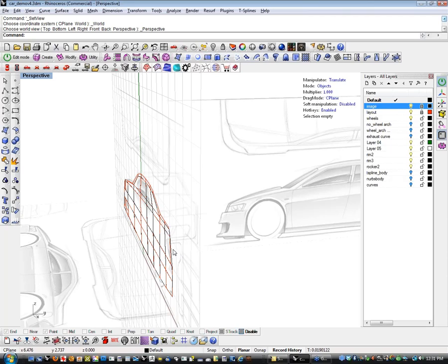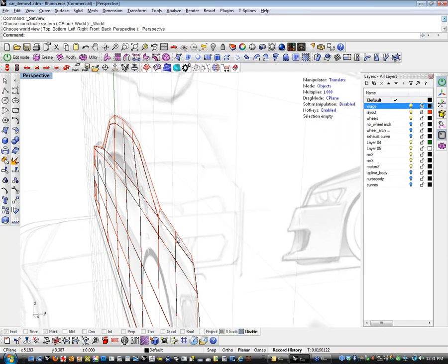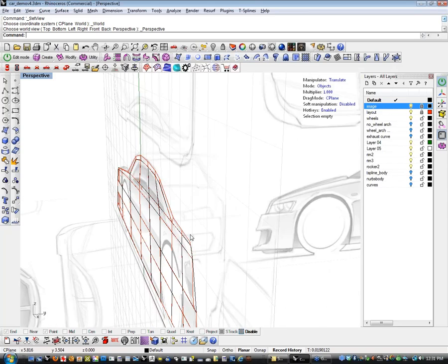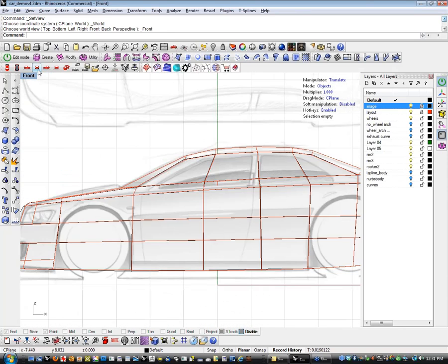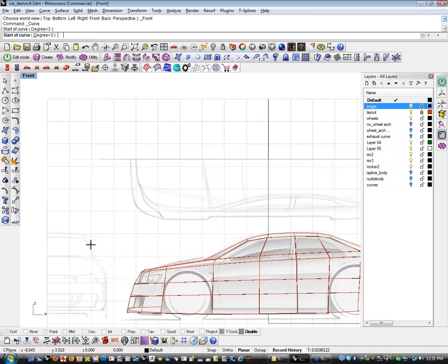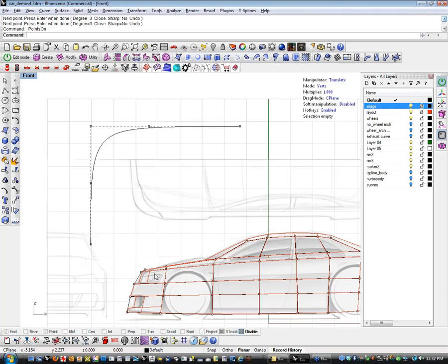Now, if I were just to bridge and have a 90-degree edge on the side of this thing, I would have a 90-degree edge, but the corner would be dictated by this point, and wherever the next point over here was, because, permit me to digress for just a second, T-Splines works just like a NURBS curve. So if I turn the points on here, if you imagine that these points are isoparams, or in this case they're points, if I pick a point on a NURBS curve and I move it here and I move it here, I get a sharper corner, right?